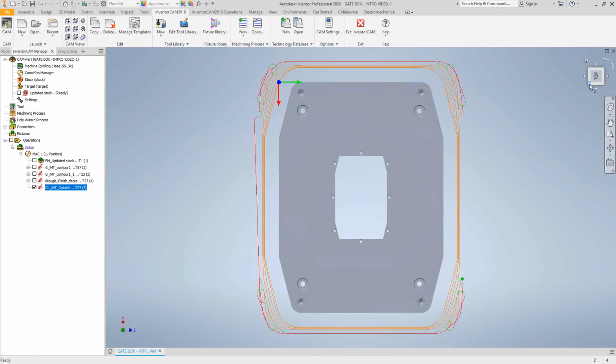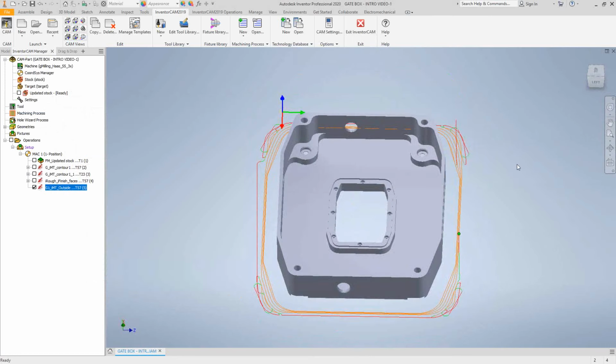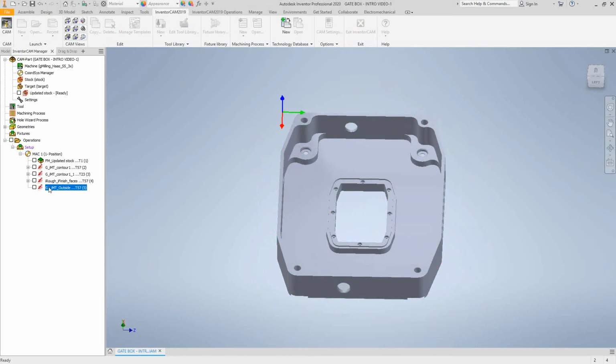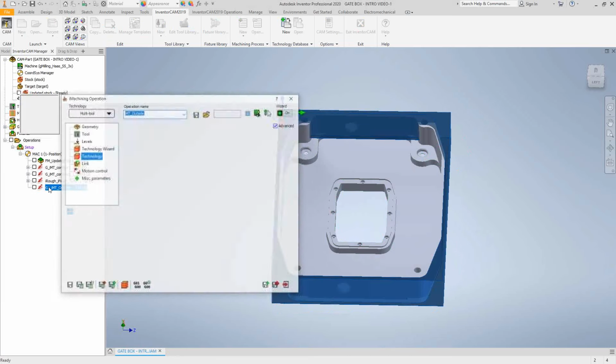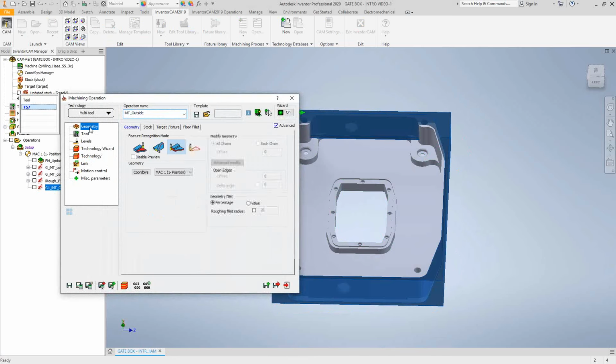When iMachining goes into a cavity, it does the helical entry. But if it can do side entry, like it has with the outside part here, or if there's any open chains that you define in your geometry, it simply does a side entry like you see on this window here. I'll reopen that last one just to highlight the fourth option. Fourth option basically works the same way as a traditional pocketing toolpath. You just choose some chains and you set your levels.